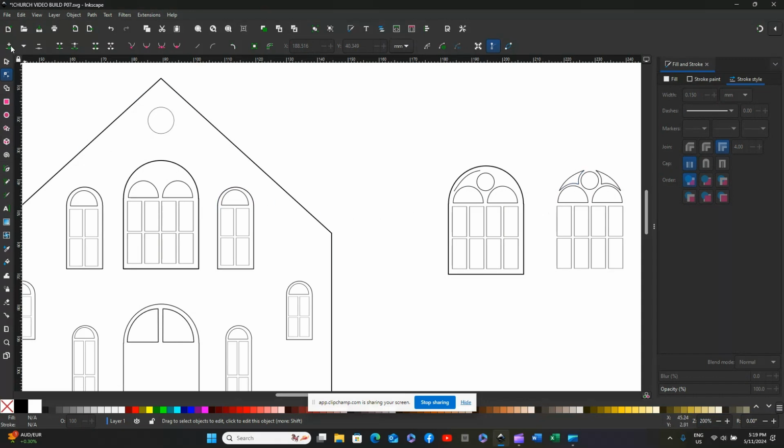So again, use the select tool, draw a line, and click on the end of there and draw another line. This time, take it in between the half circle and the circle. Doesn't matter if it cuts down a bit lower, because we can move that with the node tool again.